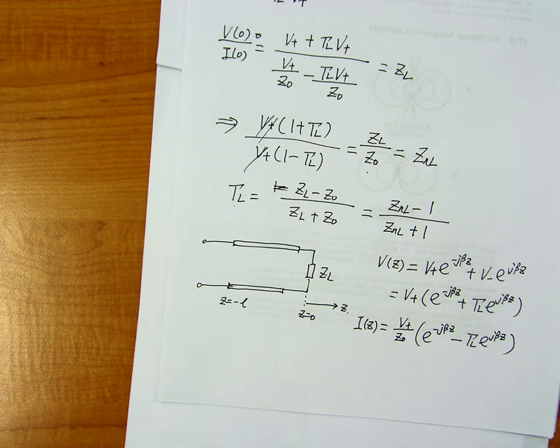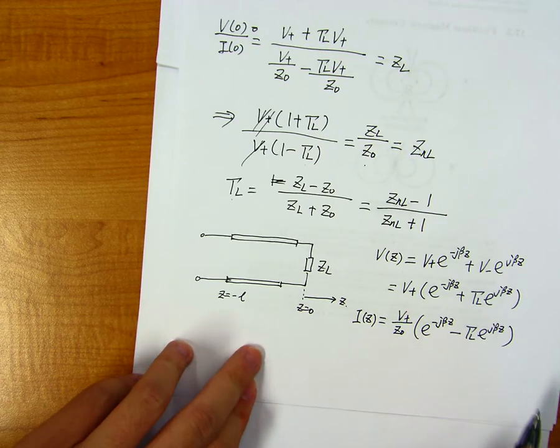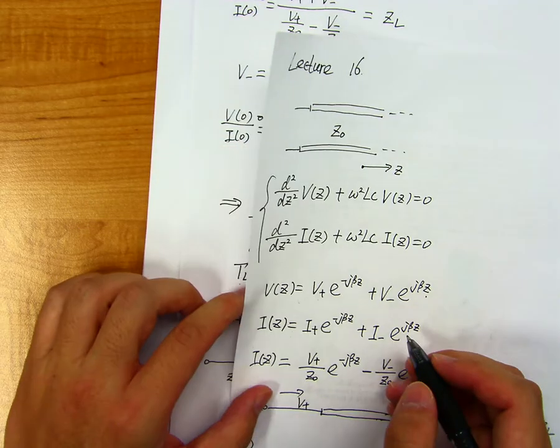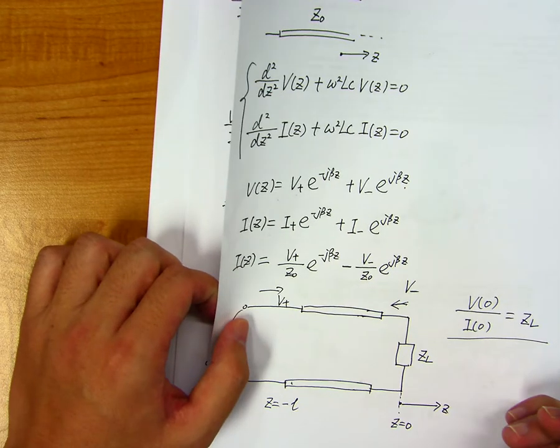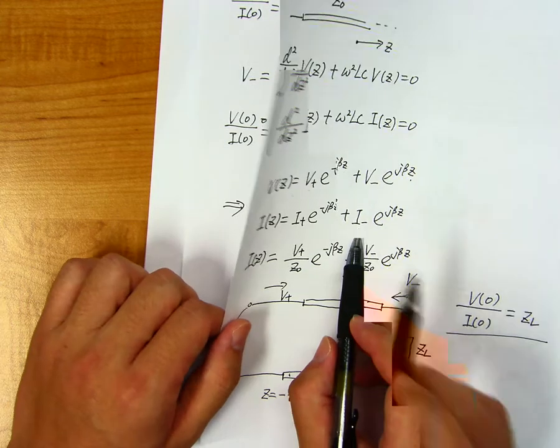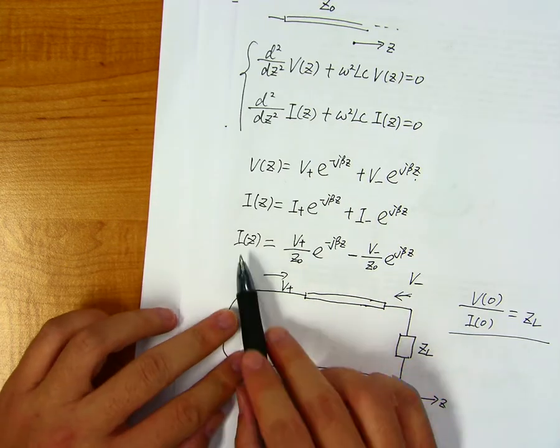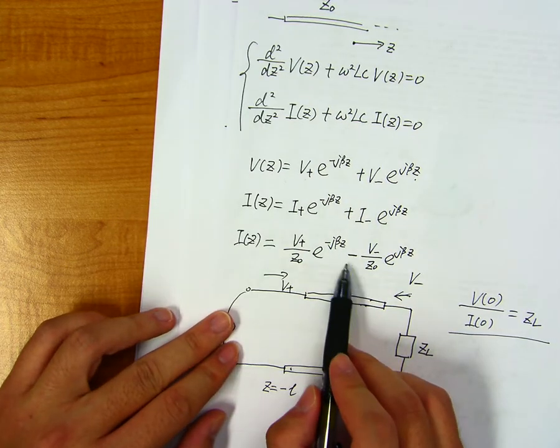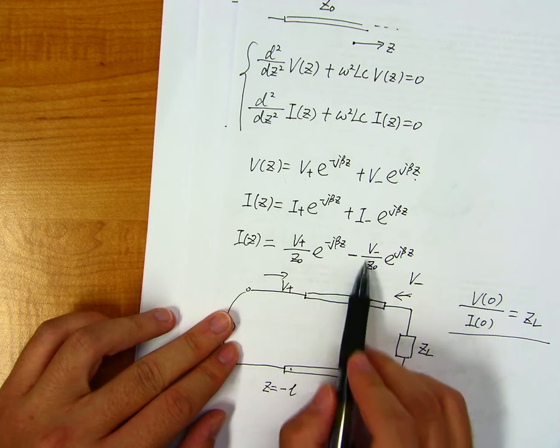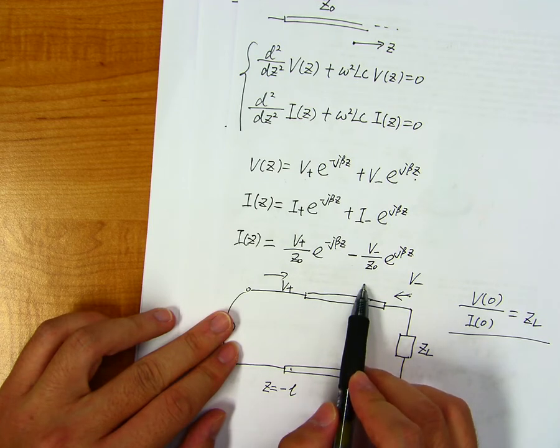When you first defined it, was it also supposed to be minus? Which one? The I. This one? On the first page, you defined it as plus, I believe. Oh yeah. Yes, it is a plus I minus, but if we express the I of z in terms of V, we have a minus sign in terms of V and the characteristic impedance.